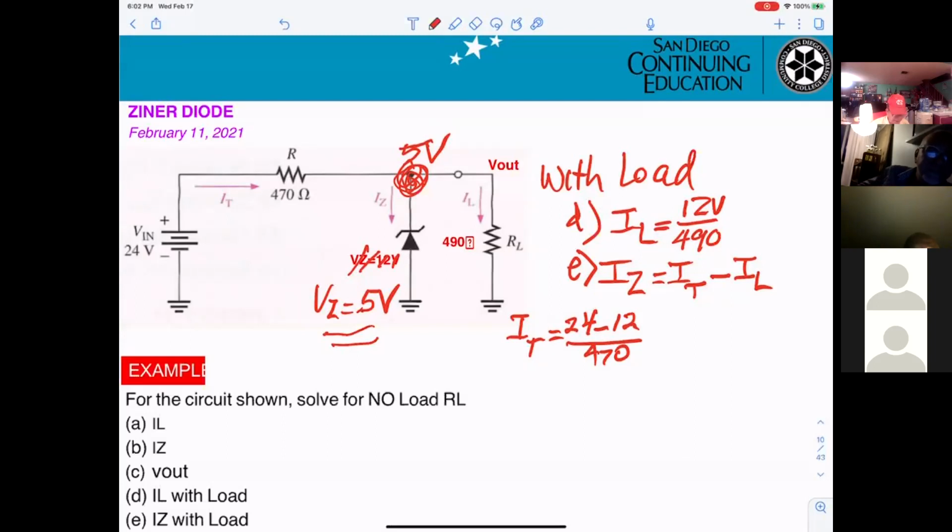However, what I'm saying here is, if the voltage applied here is 30 volts, you don't need to do any calculation. You're able to recognize 30 volts must be higher than 5 volts, then the Zener must break down. Correct.